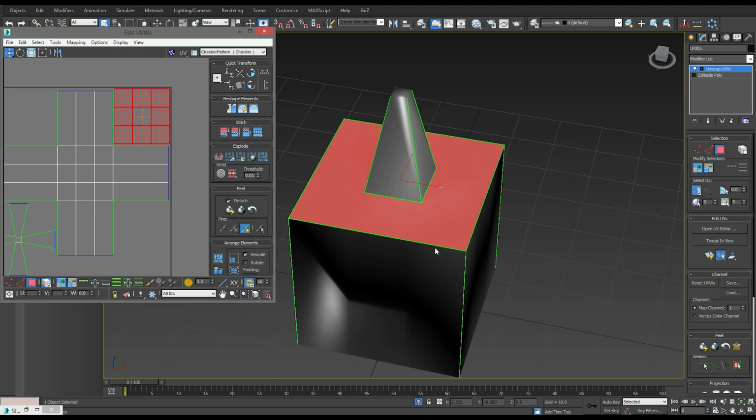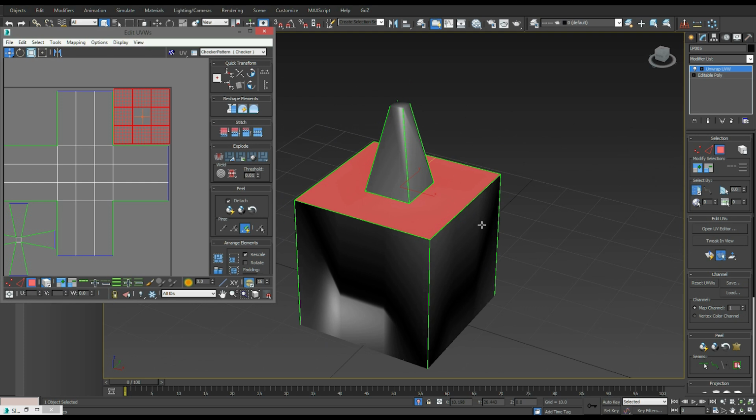If you don't do this, you'll end up with a black seam, or rather a black edge, where these two smoothing groups meet. There's actually absolutely no way to remedy this other than maybe going into Photoshop and trying to paint it out. But that's a terrible workflow, and it's going to burn up a ton of time and just totally kill the project off.